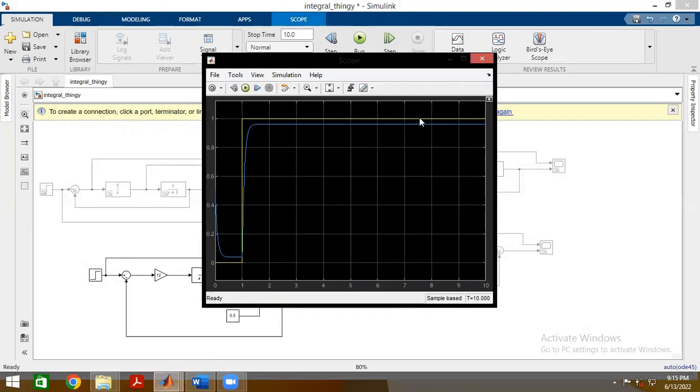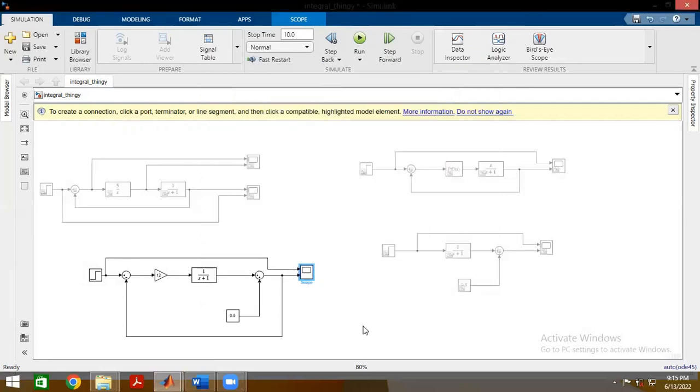Yes, we still have that steady state error that we had, and I'll show you how to get rid of that in a minute. But we are rejecting disturbances a lot better now that we've got negative feedback. So we're getting better at this. Now we've learned how to reject disturbances and inherent inaccuracies in the system.